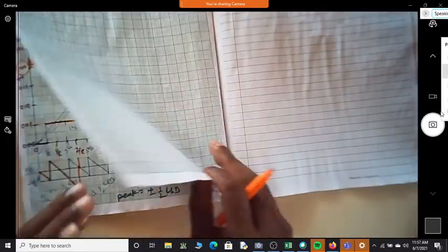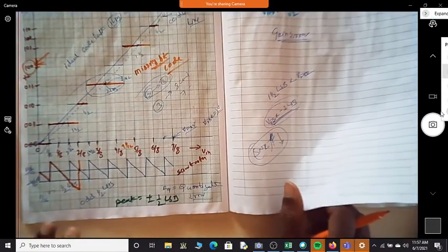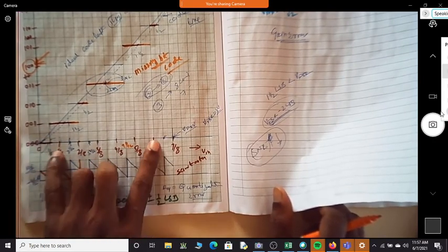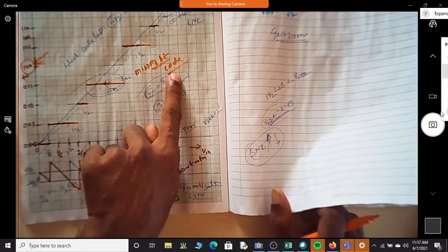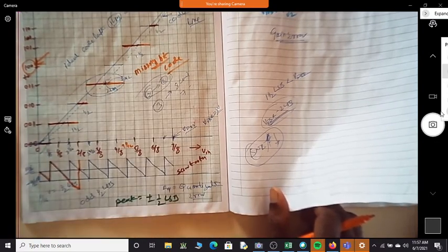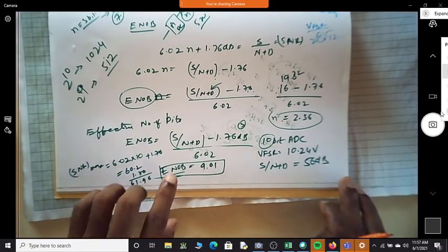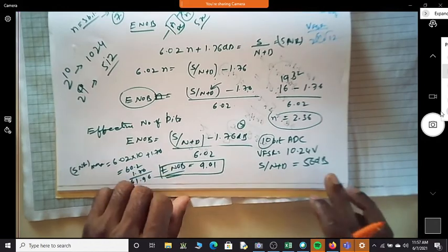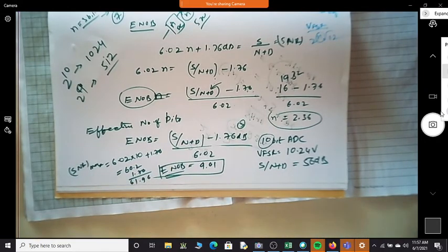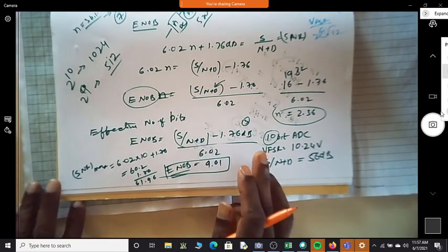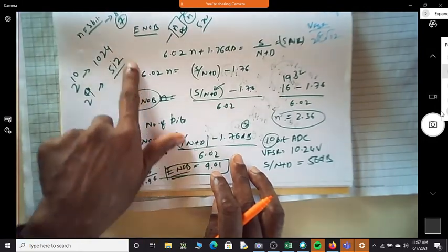This is about the specifications of ADC, where we talked about offset error, gain error, missing code, code center line, and also effective number of bits. We have an effective number of bits because the signal to noise ratio is lesser than expected. In such a case, we are going to miss some of the bits.